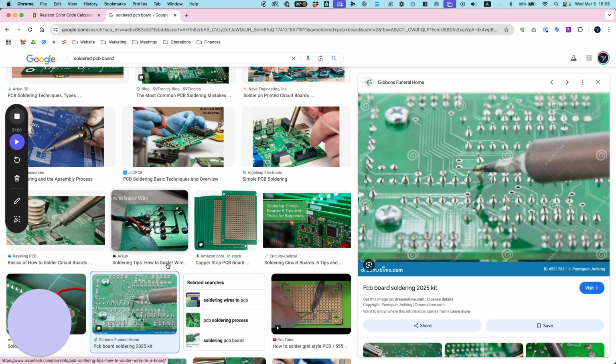Yeah. So really, you need 3 more resistors. So desolder this joint and this joint, straighten it up, then put a resistor here, here, here. So I get where you're coming from. But we want to do it this way, which is 3, just like I have on that breadboard. If you want to look at the breadboard. Did we find resistors that are compatible or not yet? Here's 2. We've got to get a 3rd one.